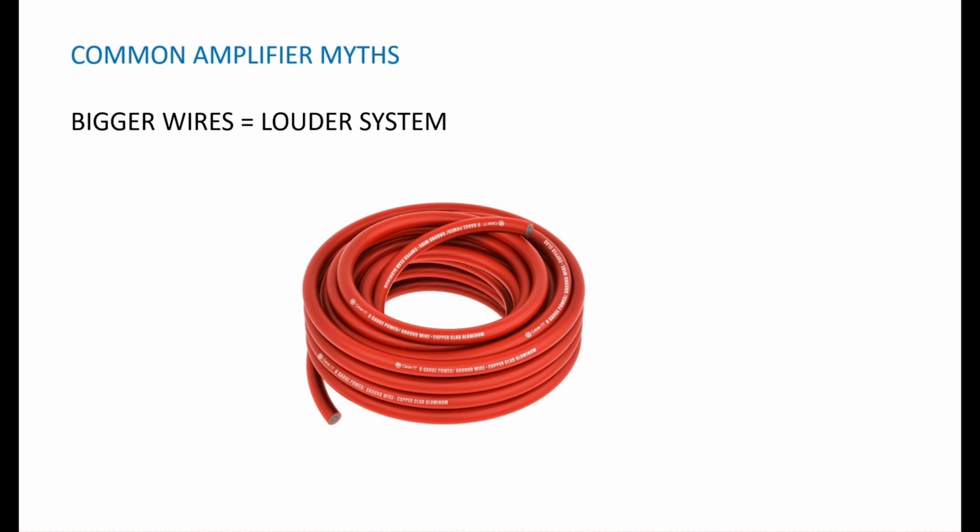And once again, the next one is kind of in the same bucket, where there's this belief that somehow bigger wires will equal a louder system, right? Once again, I'm not too sure of its origin, because more power equals louder, which is of course true, but if you're supplying 100 watts through a 4 gauge wire, it will still be 100 watts if it's running through a 0 gauge wire, right?